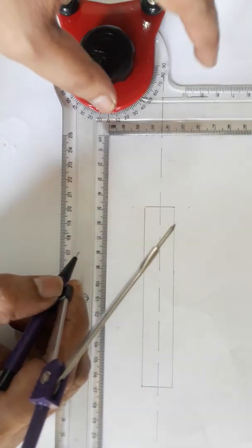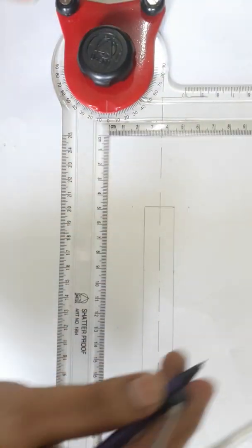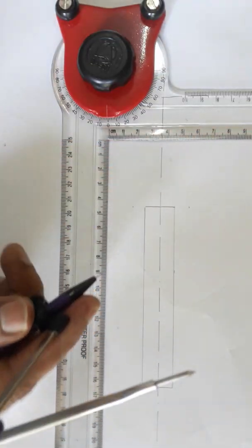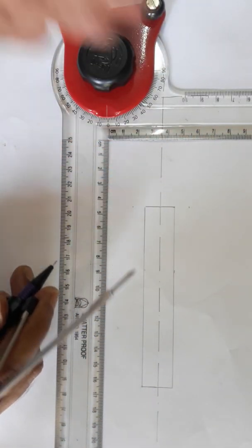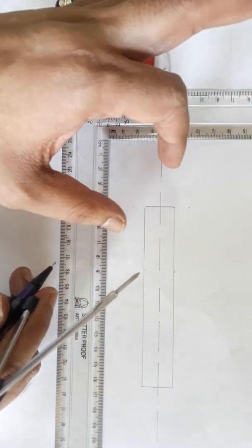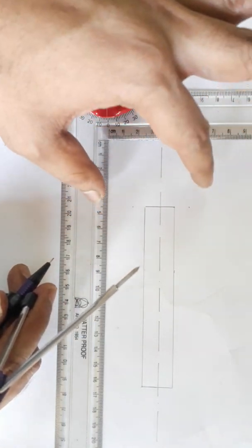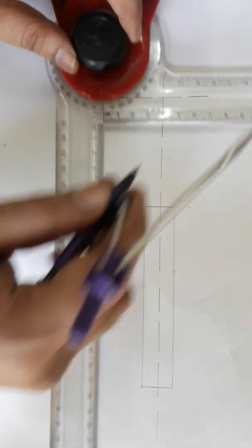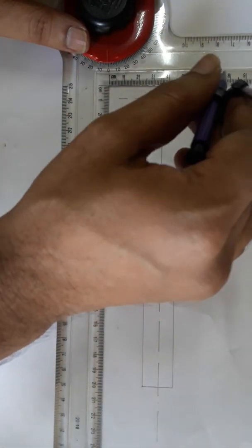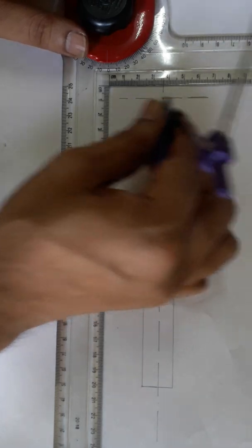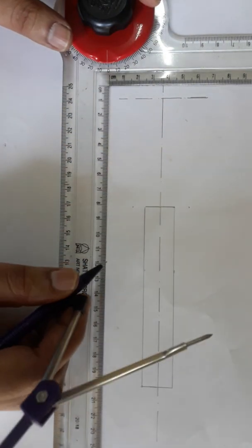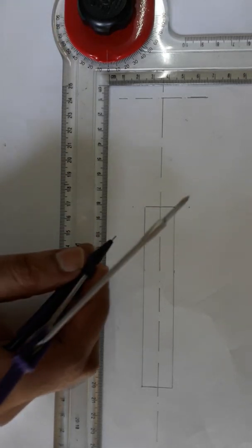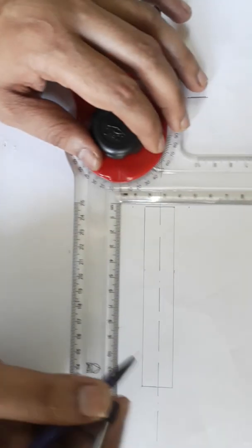But in the case of view across corner, we cannot draw the front view bolt head width directly because we don't have any particular formula for that. First you have to draw the side view, get the corner, and then project it. Since this is view across flat, we directly have the dimensions, so we can draw here.